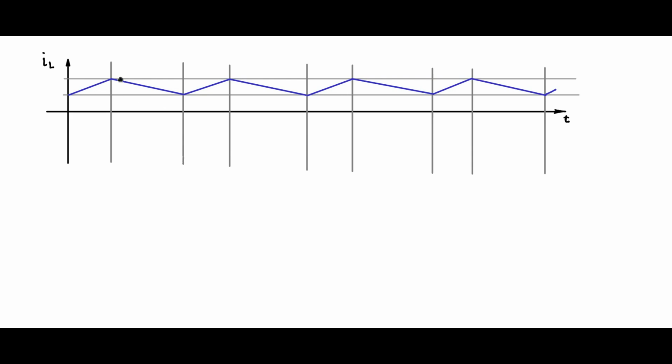Now this would be the normal expected steady state value of the inductor current. Now let us see what happens if there is a disturbance. Now I will introduce a disturbance here. I'll just offset it. Disturbance could have occurred due to any number of reasons. If this disturbance occurs, the inductor current will start on from here. It's an integrator. It will start on from here with the same slope, V in minus VB divided by L. So it will go parallel to this line.